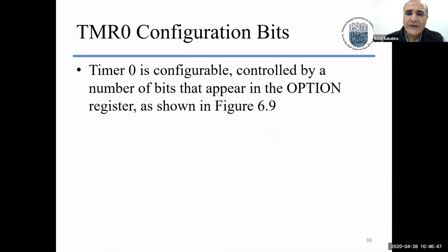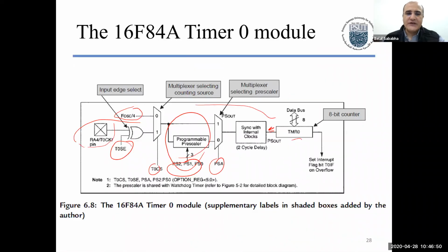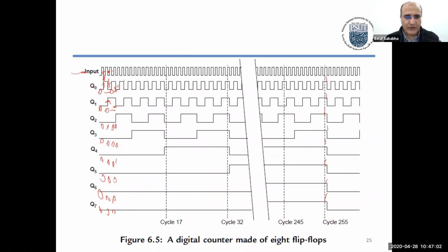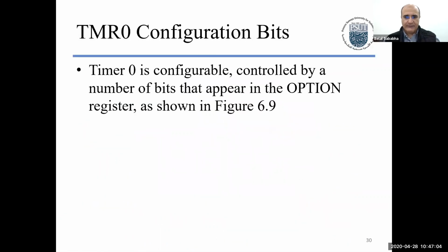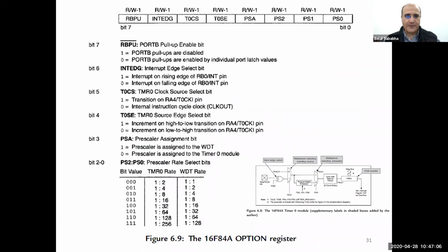So based on this, we're gonna do some math and see how to play with the time to make timer 0 overflow after a certain amount of time. That will help us. So to compute the time, there's a prescaler we're going to look at.